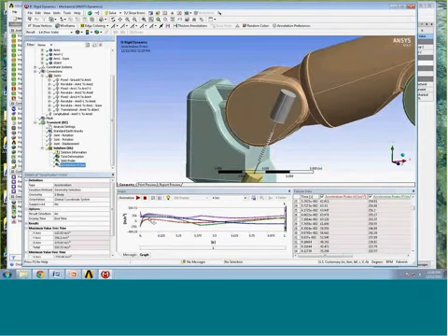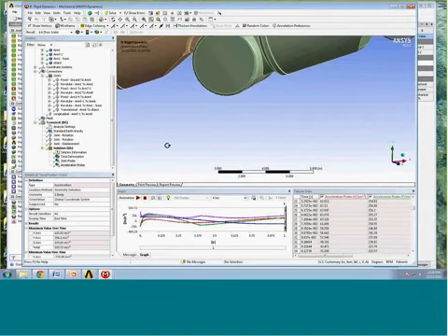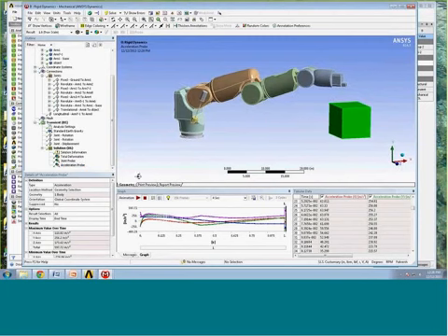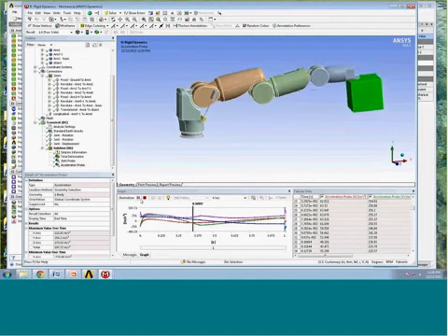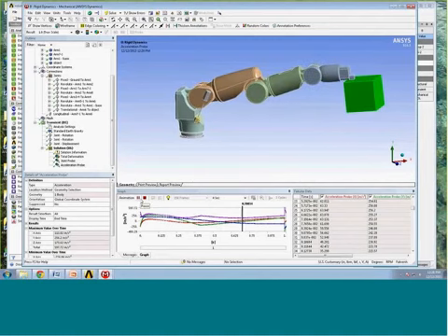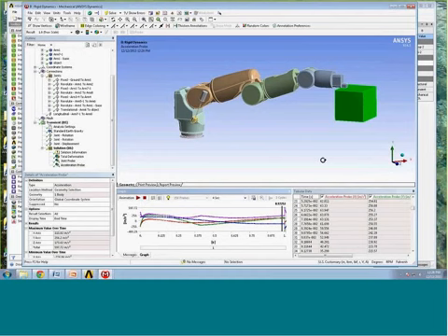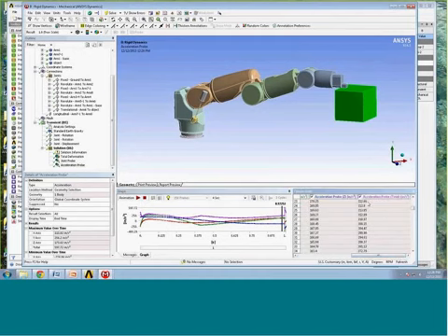The acceleration probe allows me to track the accelerations in the package. Okay, let me show that again. There we go. And so we've got some early accelerations of about 310 inches per second squared. So almost 1 g of additional acceleration above the gravitational load.